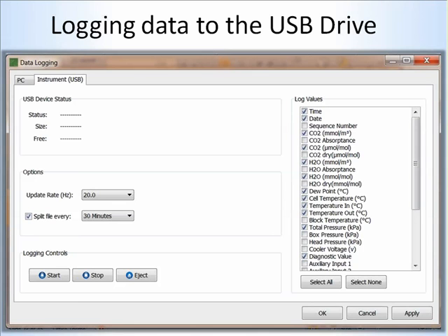To give you a better example, if you're collecting at 10 hertz, again collecting carbon dioxide, water vapor, methane, and all the associated variables, all 52 of them, kind of a worst case scenario, you're going to have about 4 megabytes an hour. That comes out to about 40 days. So your USB drive could hold about 40 days' worth of data.